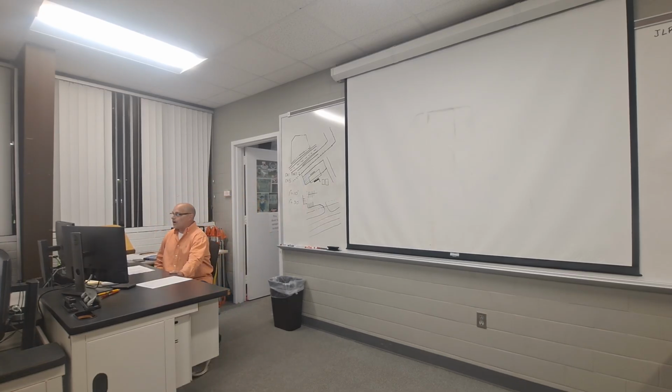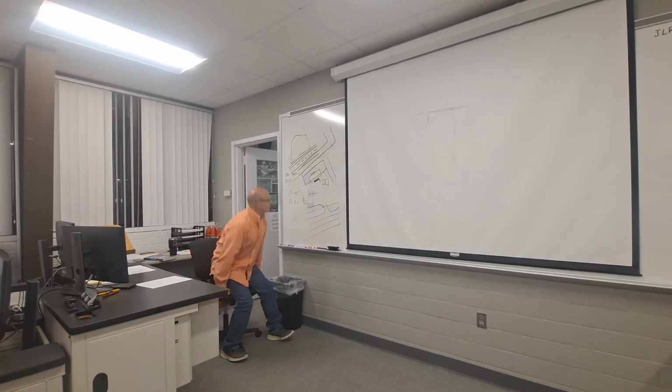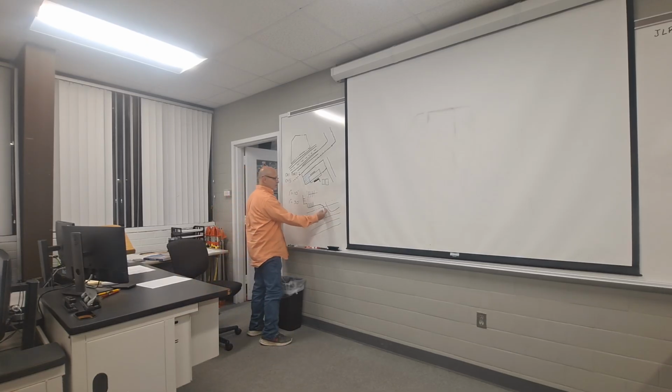So offset your property line 10 feet, that'll be the start of the shoulder. Then it's shoulder, lane, lane, shoulder, each one of them 15 feet wide. Anytime that you turn with your drive, so we have vehicles coming in, turning this corner, if we had vehicles going that direction, we'd have to have that arc right there. We don't want them dropping off the concrete.